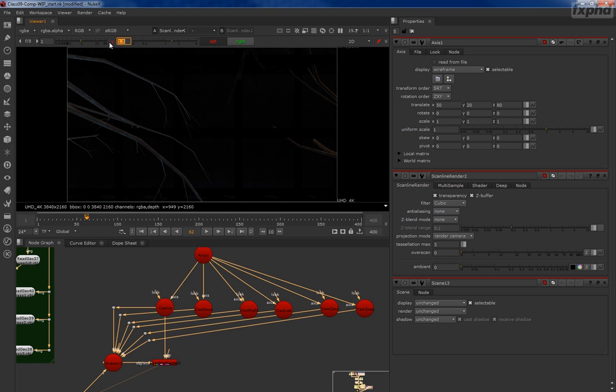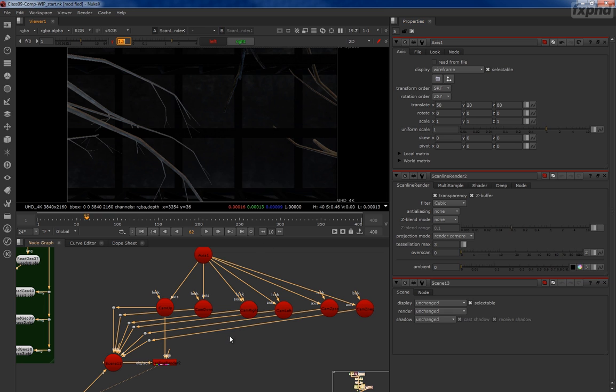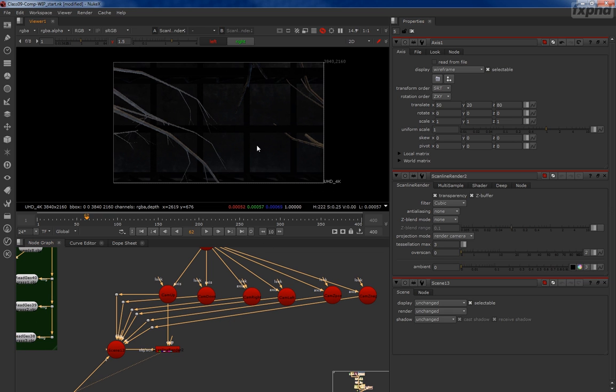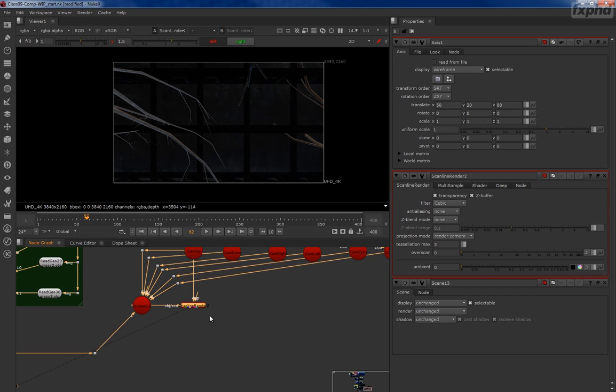All right, so let's give that just a little gamma boost so we can see it. Now, it's going to become incredibly inefficient to be rendering 4K renders for 6 cameras times 2, so 12 cameras at 4K for every single camera. And also, the resolution's wrong, the aspect ratio. Remember, these cameras have 90-degree field of views and 45-degree focal lengths. So they're square.